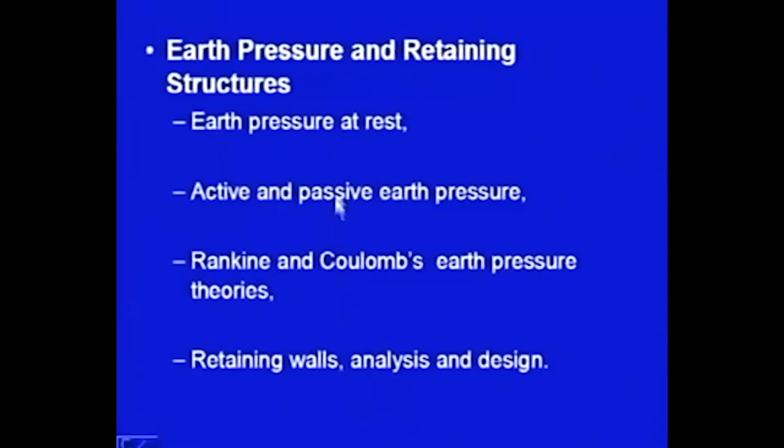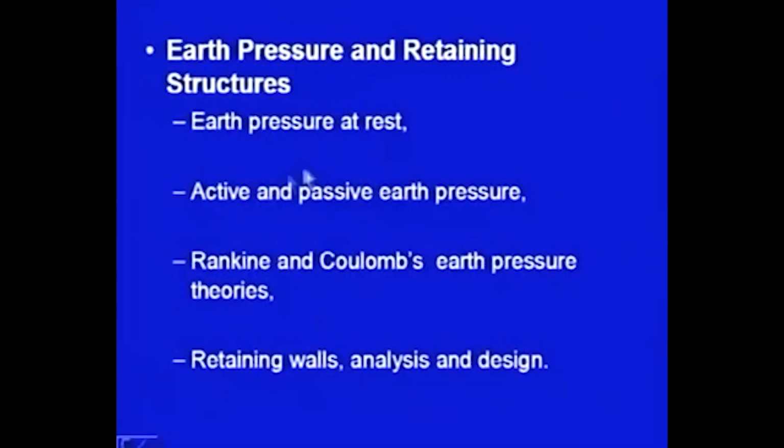Then I will move on to the next chapter, which is earth pressure and retaining structures. The earth pressure theories are very useful in designing the retaining structures like retaining walls. So, we shall be considering them in detail. I shall start with earth pressure at rest. Then I shall be discussing active and passive earth pressure. Then there are certain theories, Rankine theory and Coulomb earth pressure theories. We shall discuss those theories in detail, and then finally I shall be taking up the design, the analysis of the retaining walls.